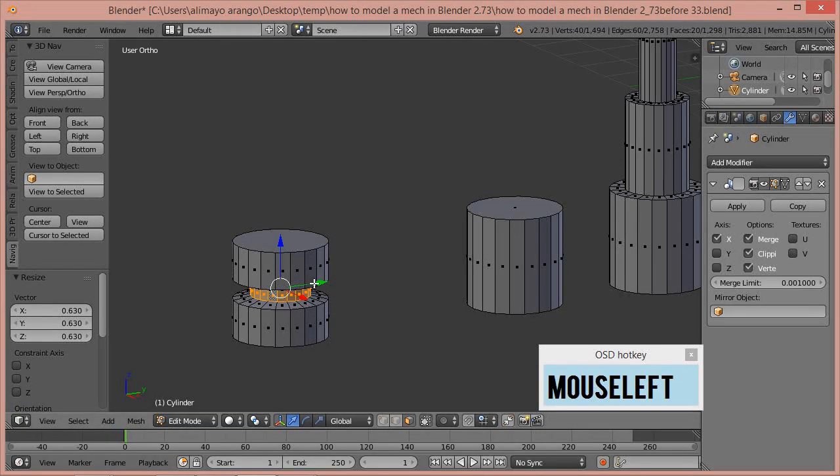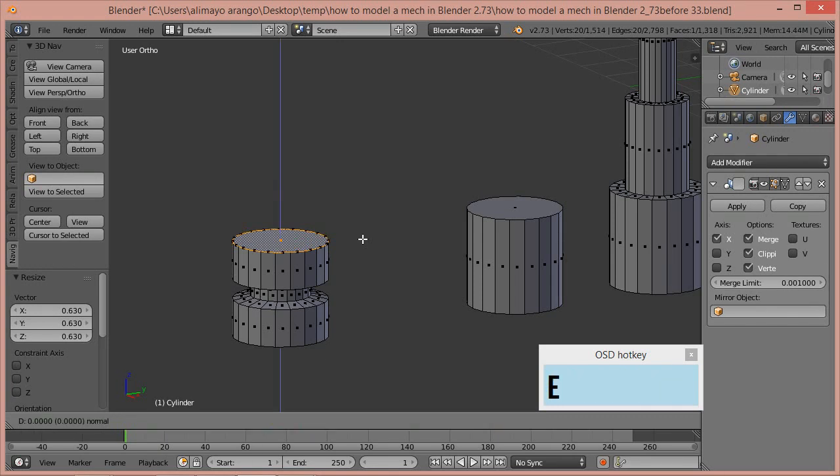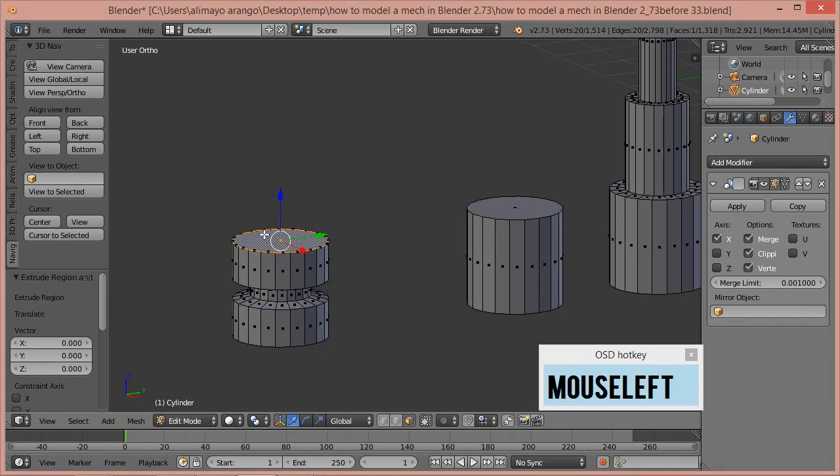So what we're going to do now is select this face right here. When we selected it, that automatically deselected here. Sometimes you want to have something be exactly the same as another piece of the same object. So if this was a mirror, we had it turned to our side, whatever we did here would be mirrored to this side, right? One way to have things be the same and get around that is to use direct input. So we're going to hit E to extrude, left click to lock in, right? So we have our extrusion.